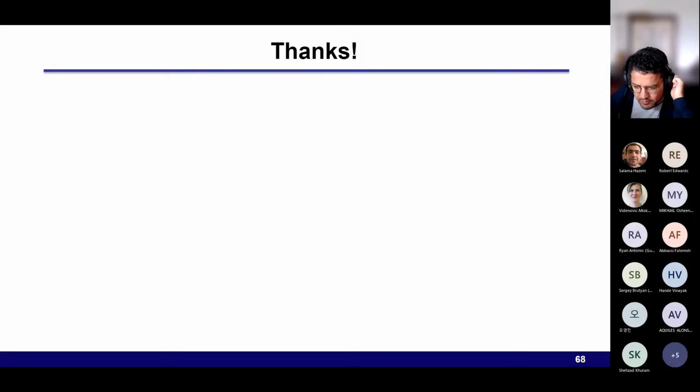Yeah, that's a good point. I just want to correct something. We still do AC simulations for the PLL and RF designs. Prof. Wenzloff would be a good reference to talk about it because he's the one leading that. But regarding your question, for the PMU, for instance, one of the simulations takes about 2 days in GF12 using closed tools. In Skywater, depending on the extraction you're making, it takes from 8 hours to a day or two.